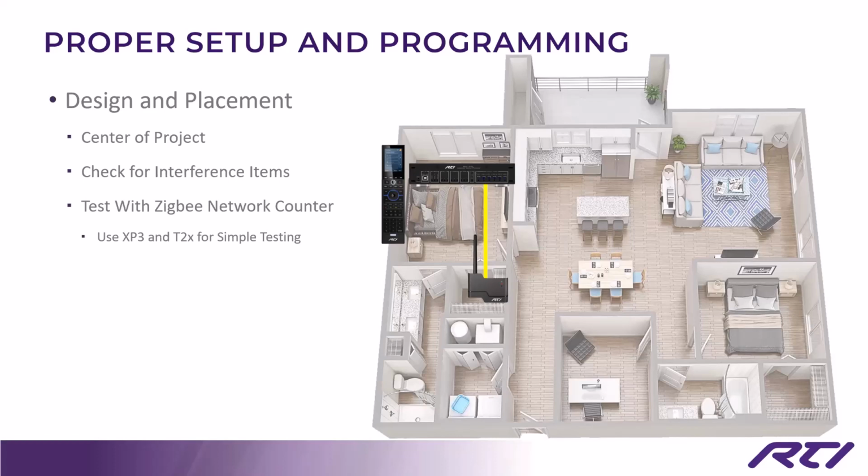if you have a couple of those in hand to just keep on hand and use as your test bed, it's a very easy way to not have to drag a ton of equipment in and be able to utilize that Zigbee network test driver as a way to test where that range is going to be. Okay, so just keep that in mind. And we'll show you how to use the Zigbee network test driver in just a moment.